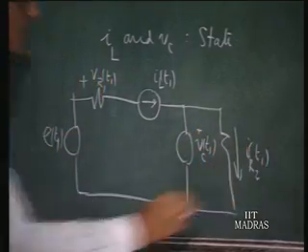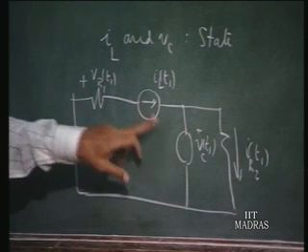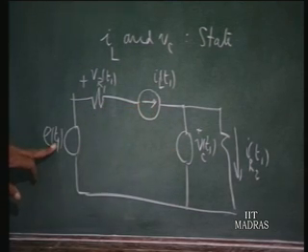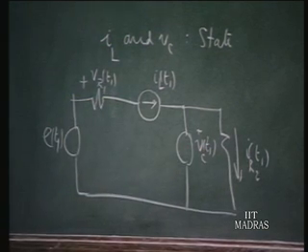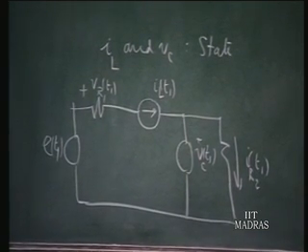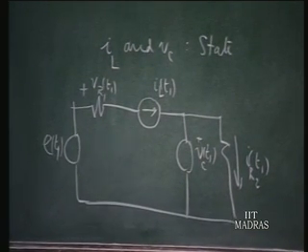So, if you know the state at particular point t1 and you know the excitation function also at t1, these values can be calculated purely as in a non-dynamic system, purely as a resistive system, because we now have a purely resistive network under the influence of several sources, and the solution is one that pertains to an instantaneous system or a non-dynamic system at that particular point of time t1.